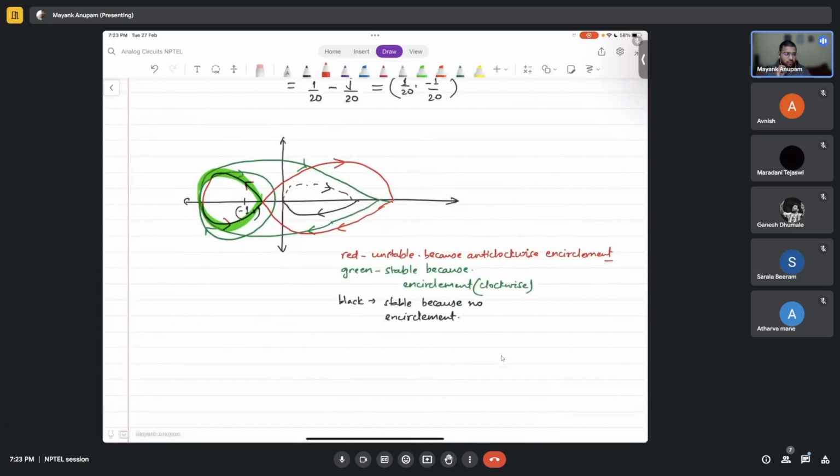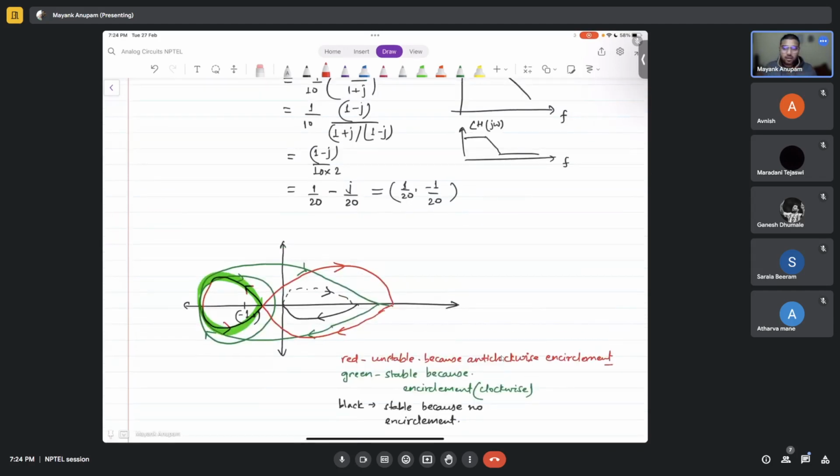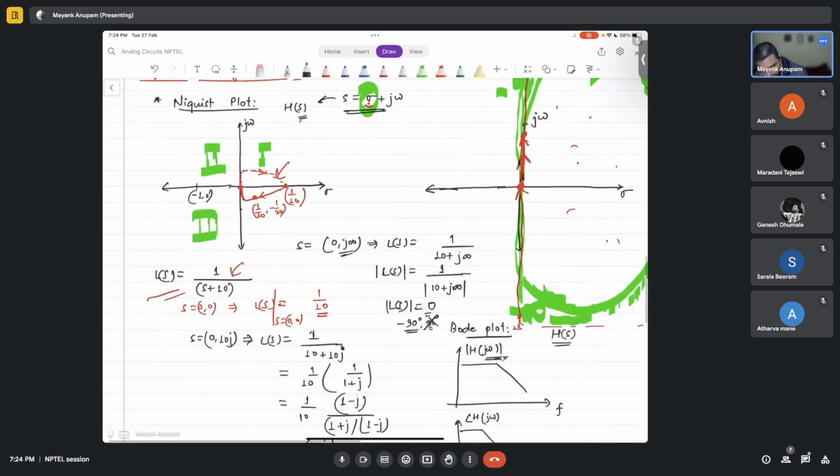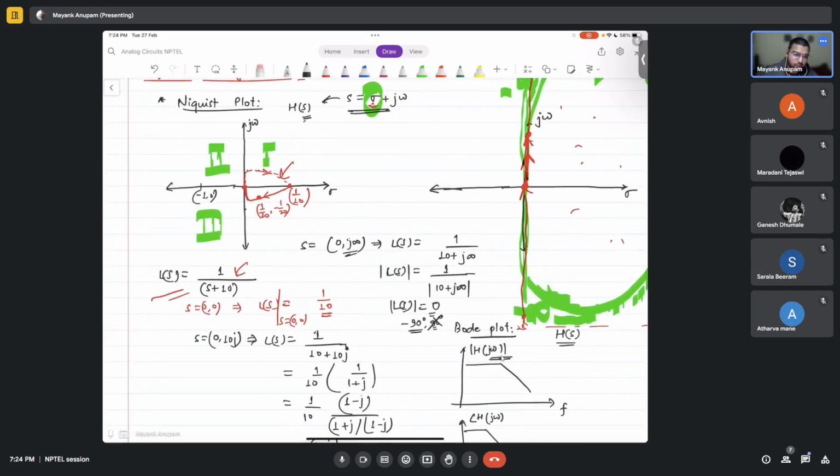And now the rest of the things I think the instructor explained clearly. You can again go back to the week 4 videos and watch them again. You may be able to get some new insights. You should be able to understand why he was saying that with two poles the system can never be unstable. With one pole the system can never be unstable. You can clearly see this is an example. The first one, this L of S here, is an example of a system with only one pole, right? There is only one pole in this negative feedback open loop transfer function, correct?